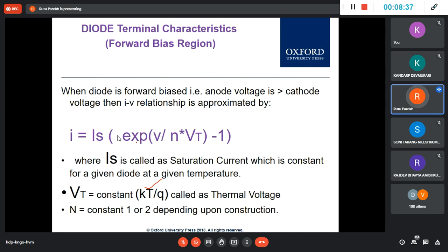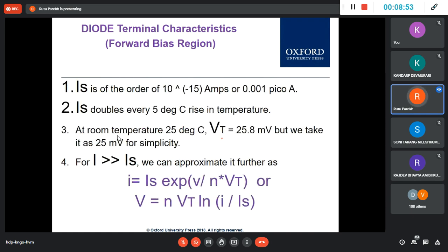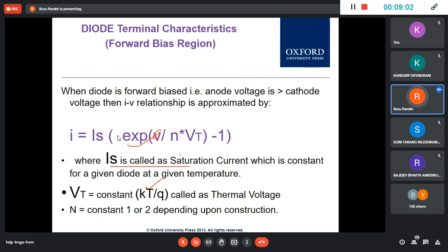So this is your diode equation. This term will become small because V is negative now, and this is what is dominating. So your I will be equal to minus Is, and that Is is the saturation current, and the range of that current is in nano, pico, right? That is the order of this. It's a very low current in the reverse biased,